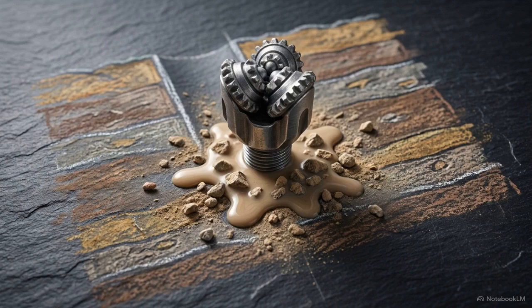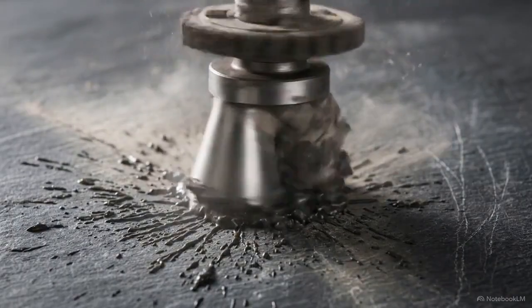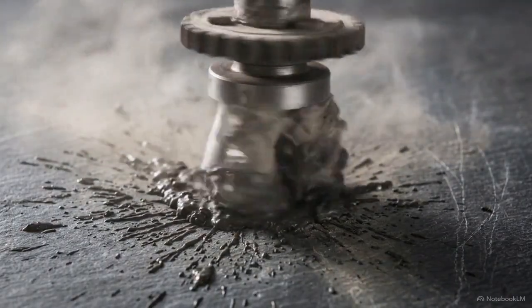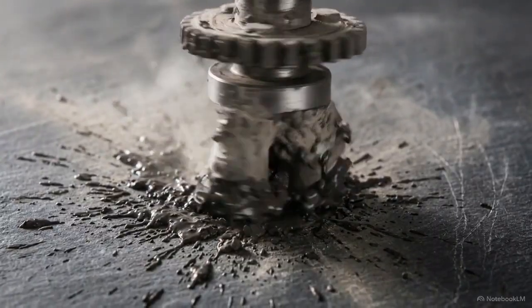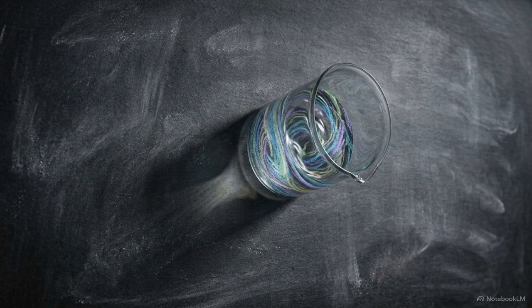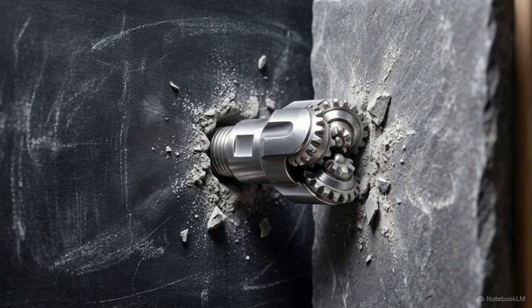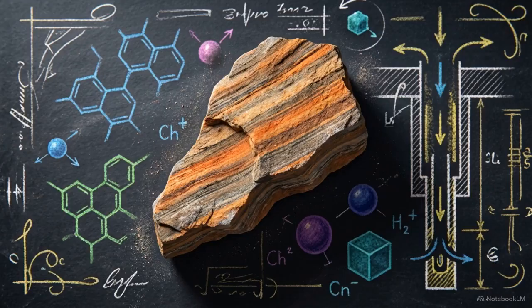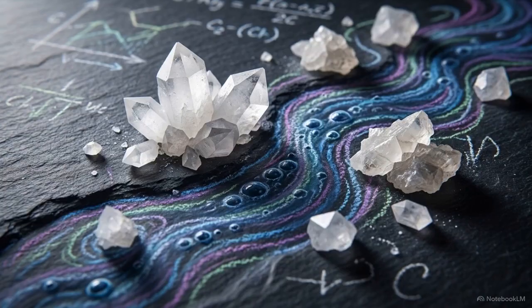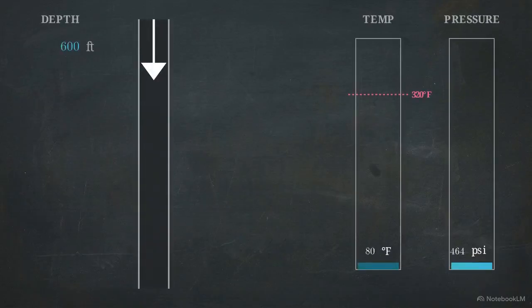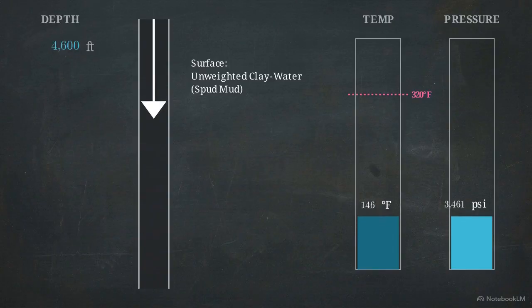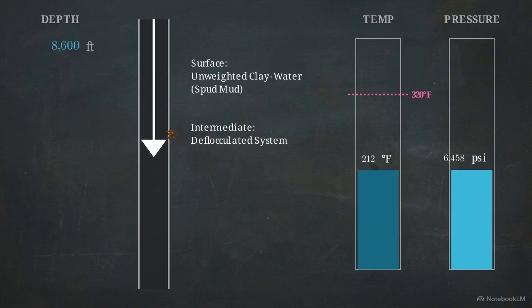The water-based drilling fluid used to spud a well at the surface is engineered for shallow rock, but pump that exact same fluid to extreme depths and the resulting chemical failure will destroy the wellbore. These fluids exist as active chemical equilibriums, governed by specific applications, the surrounding geology, severe downhole contamination, and rising temperature. We track a fluid's evolution from a surface spud mud down to a 400-degree high-pressure reservoir.